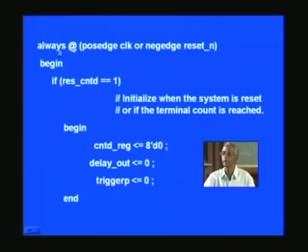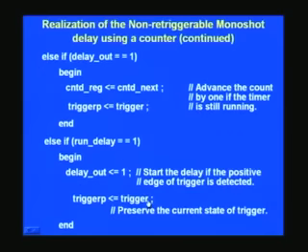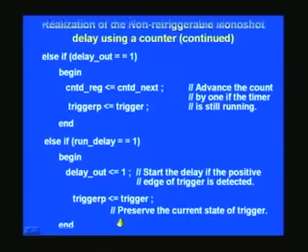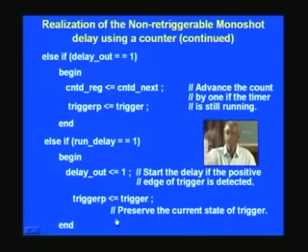It goes out of the always block, right? No other statements occurring later on will be entertained. Similarly, if this is not satisfied, only then will it go to the next one, and if that is satisfied, it will execute it and once again come out of the always block, and so is the case for every other one. So this implies it is a priority encoder.